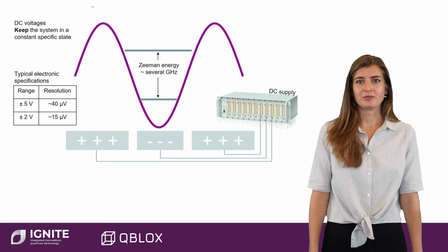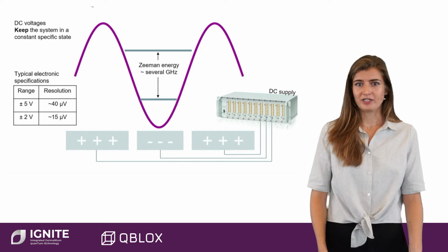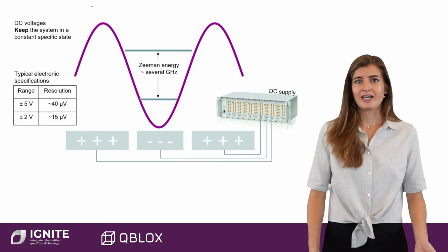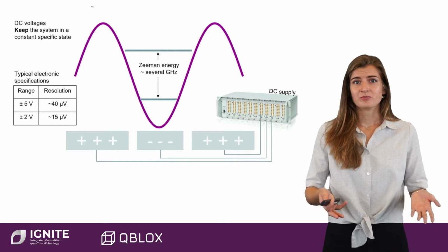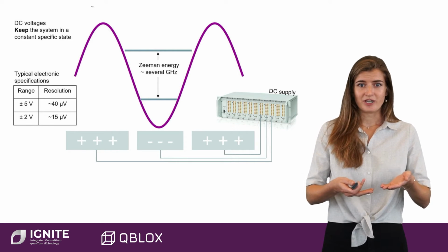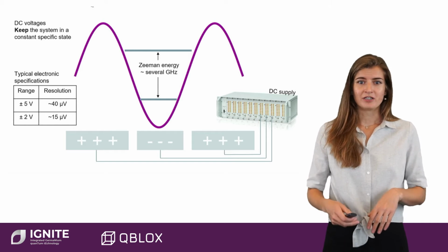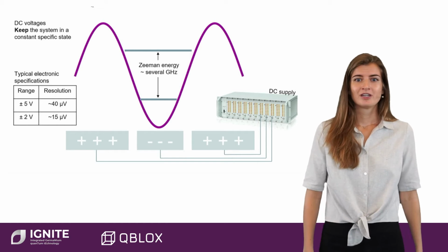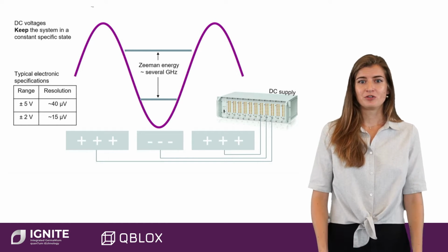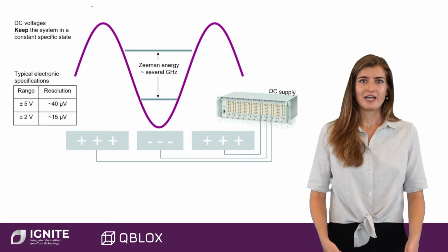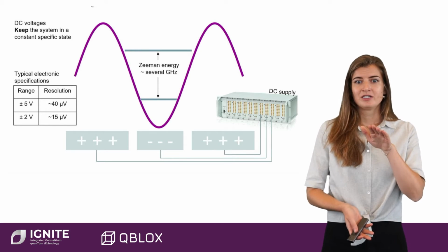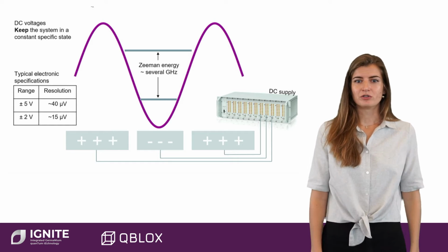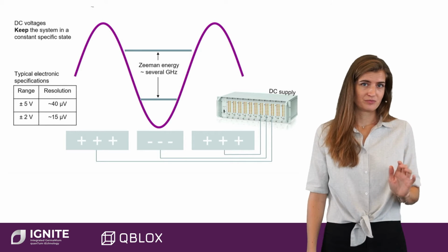Device-specific voltage requirements depend heavily on the material platform, material thicknesses, and gate configuration, as this will determine the physical size of the quantum dot, its energy level spacings, and the electrical coupling of the gates to the dot. The two-level system for the qubit can be generated by applying a constant magnetic field to split the degenerate spin states. Typically, this is tuned to be on the order of several to tens of gigahertz.